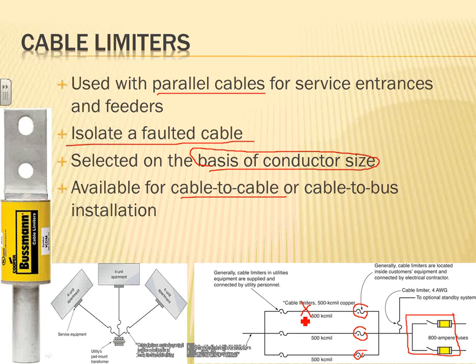There will be a situation where if one of them is to trip, it could overwhelm the other 2 sets and it will overload them and they will trip. But that will be, if I dare to guess, probably 20% of the time. 80% of the time, if one set is to trip, the load will shift to the other sets. You isolate that part and you work on it. And who cares? Your system continues to operate. The survivability of your system.